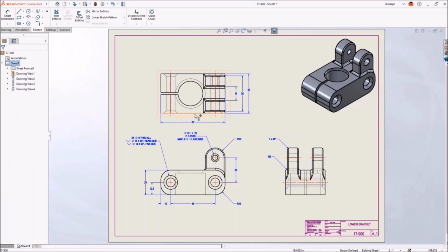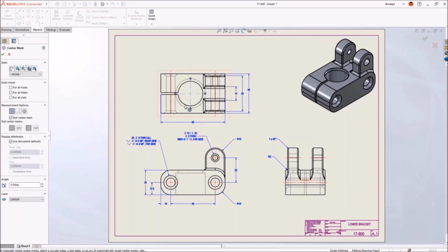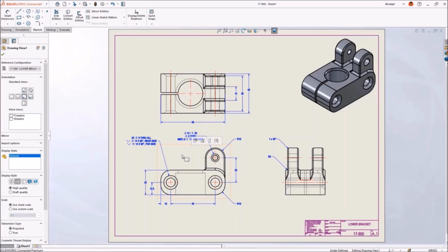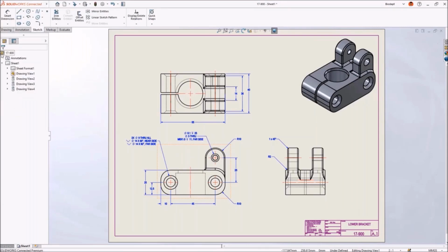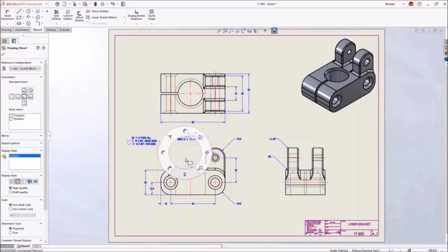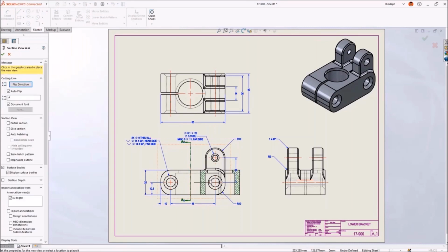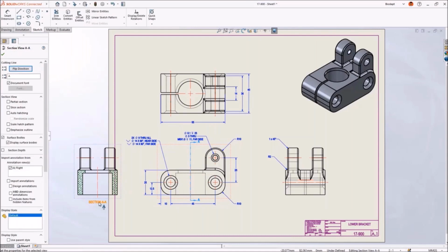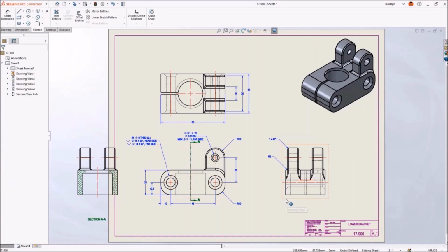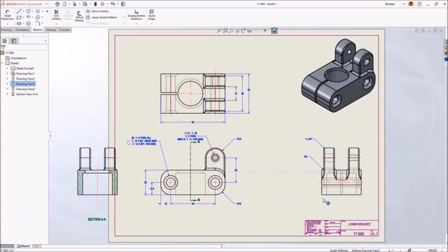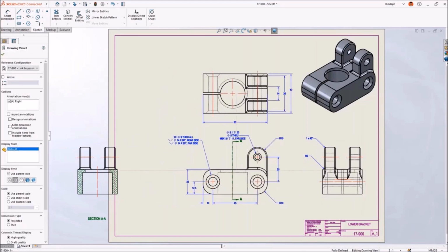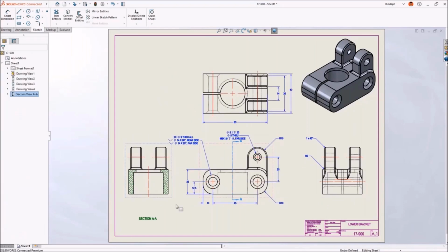Okay, so let's add some annotations, just like center marks. From the manufacturing point of view, adding some center lines here also in the front view. So you can use mouse gestures, and many customizations can be done from the user interface in the recent SolidWorks enhancement. Adding some section view and some detailed annotations for it. Okay, let's adjust our standard view to place this section view on our sheet, adding some dimensions.